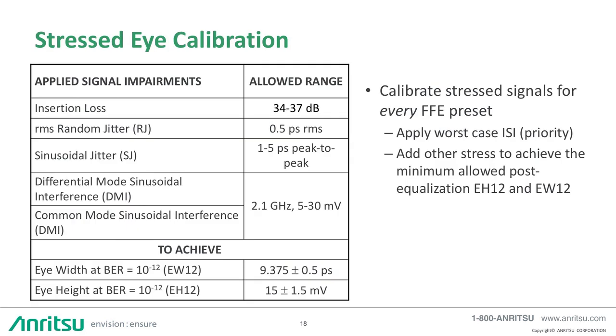Calibration of the stress signal is an iterative procedure that involves application of signal impairments and optimization of the oscilloscope continuous time linear equalizer. The stress signal must be calibrated for every FFE preset, and every condition must comply with the specification. That's a lot of different signals.